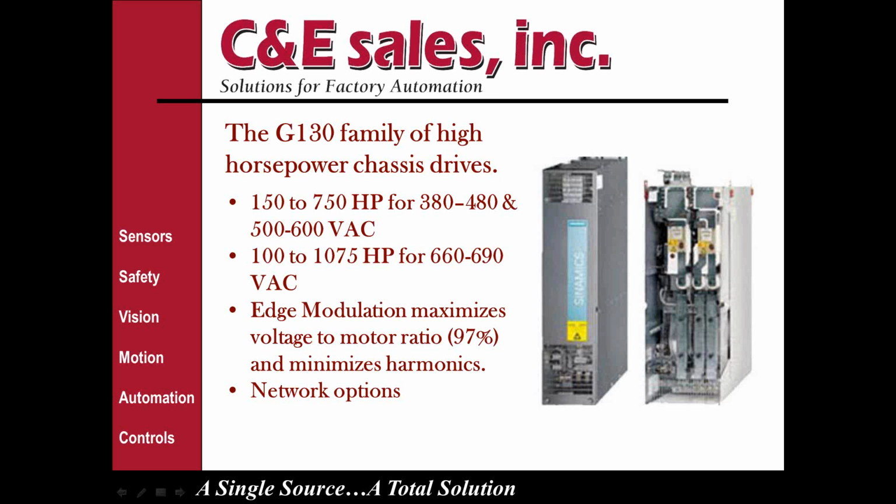They have a special feature called edge modulation, which is the technique that is used to set out the frequency going to the motor, and that allows you to get a very high ratio of incoming voltage to voltage to the motor of 97%, and yet it minimizes harmonics.